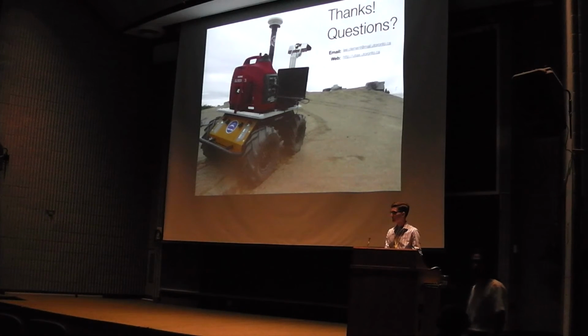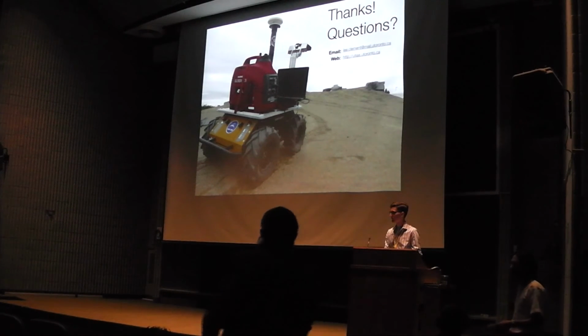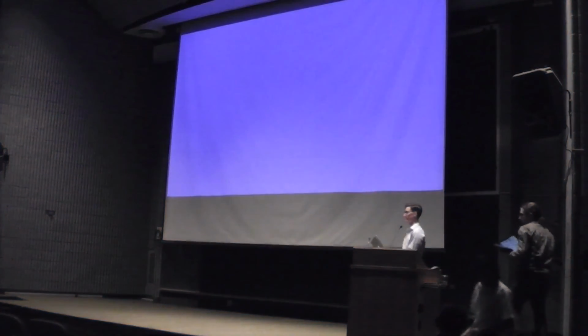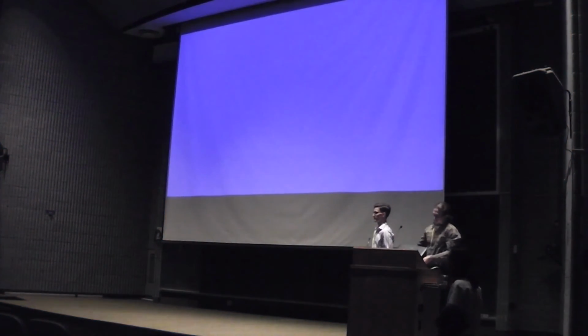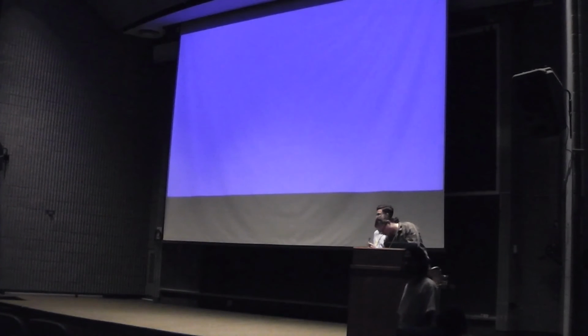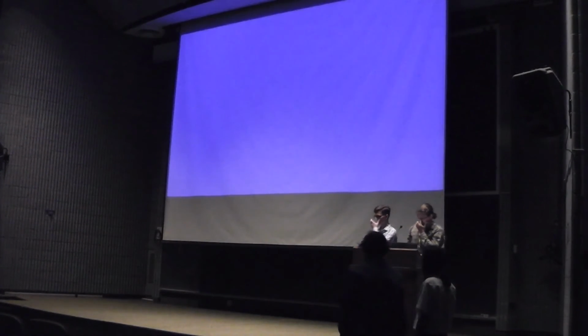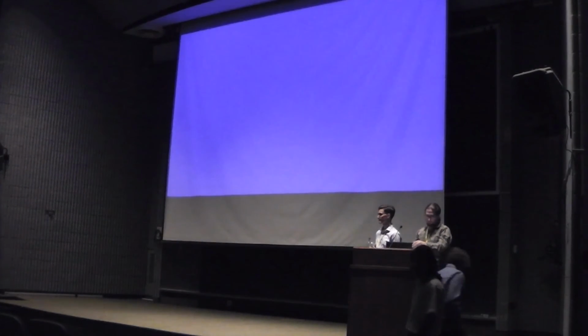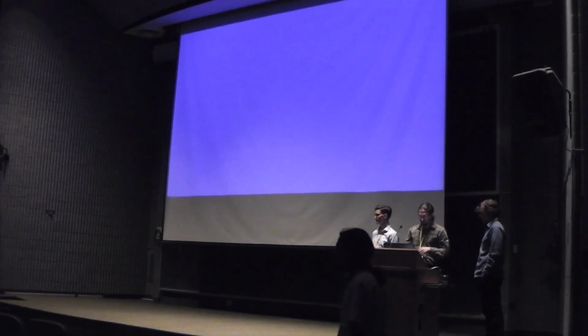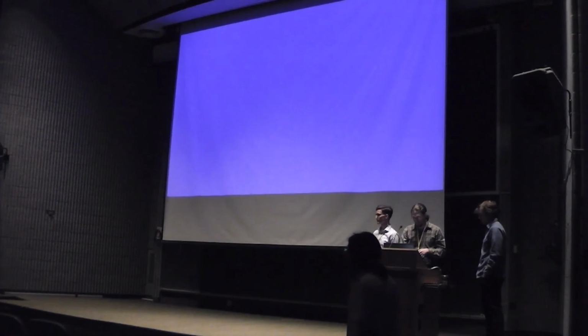I guess it wasn't clear to me what exact features you were using, but one thing that we have found, especially when we're using monocular SLAM techniques like ORB-SLAM and variants, is that if you have between 15 to 30 FPS, and depending on how much incremental baseline you're getting, direct methods can really help you in getting your pose, because all you have to do is align two images together using just the gradient intensities, especially in the kind of featureless environment you're working in.